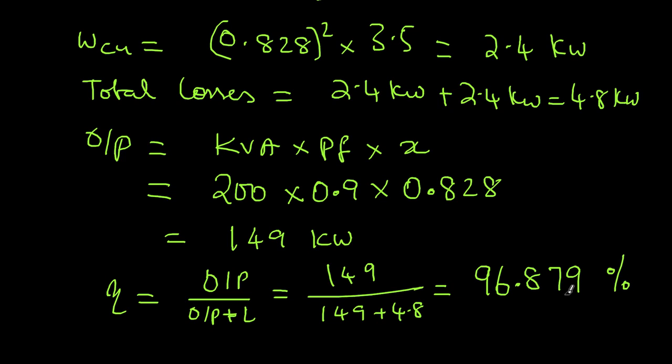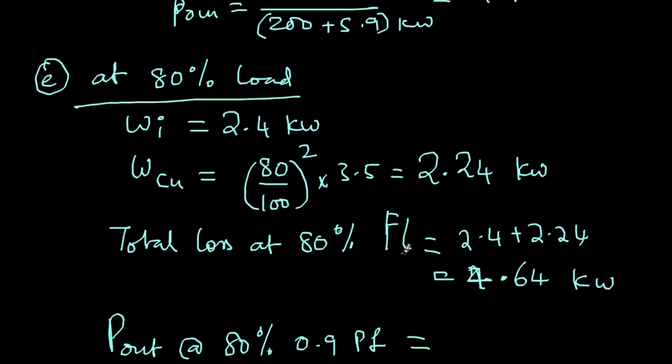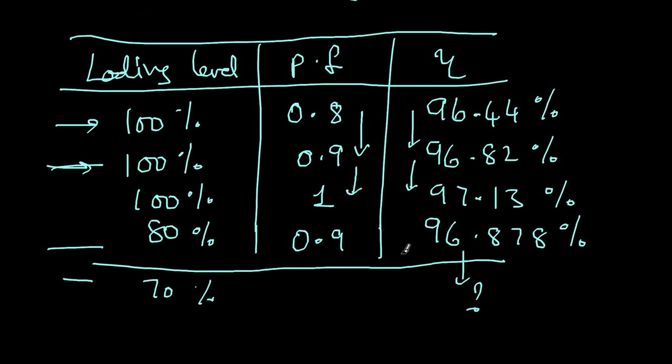Percentage. So this is the efficiency maximum. So let's verify with our earlier results. If I verify with here, you say, wait a minute, what about here? I am getting 0.9713. You are getting this because the power factor was 1. So you should compare all the values where the power factor is 0.9.